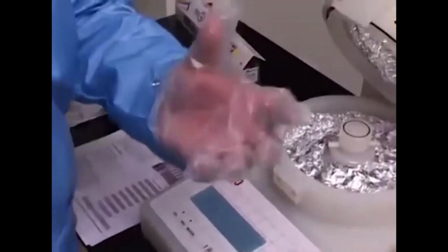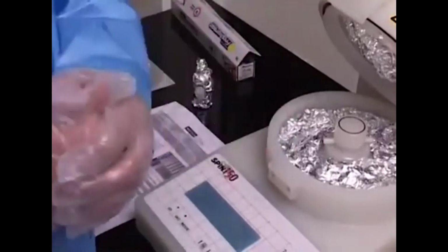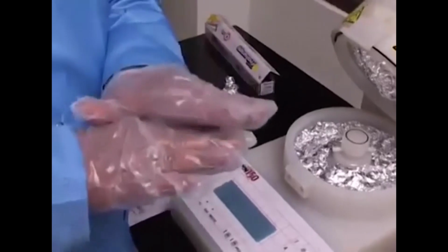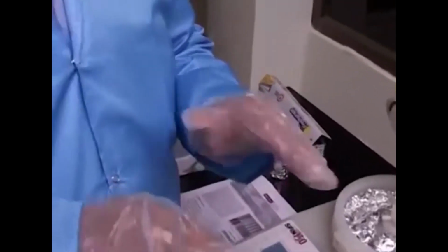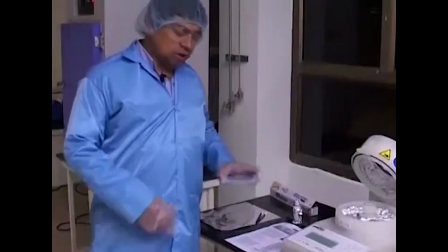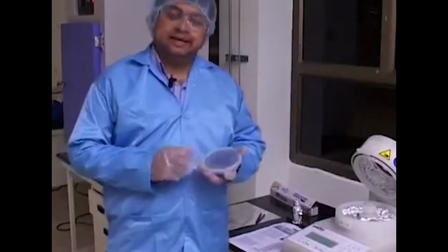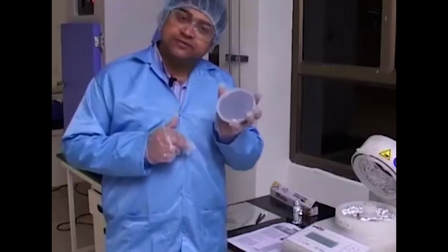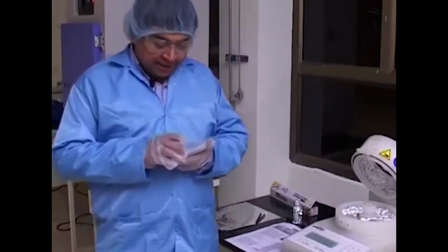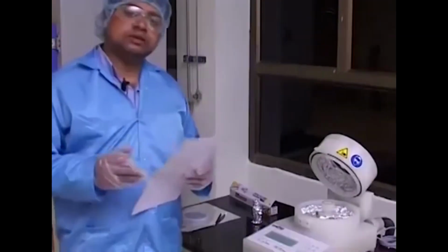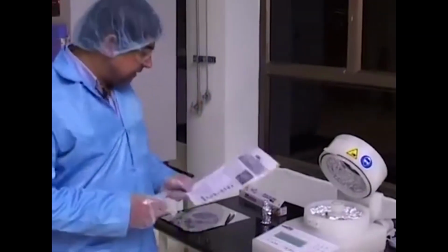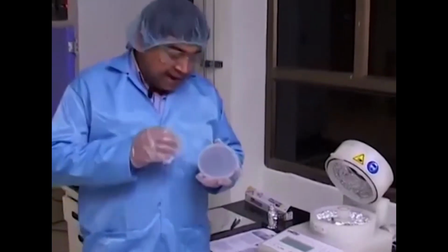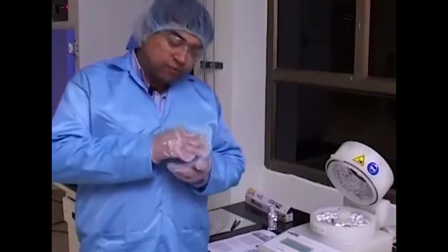When we are talking about a circular wafer, what is very important for us to understand is that first of all, the resist that you are putting should be sufficiently covering the wafer. What we are doing is spinning the resist on the top of this circular wafer, which is about 4 inches or so. The particular spinning operation should be able to adequately cover the whole wafer surface.